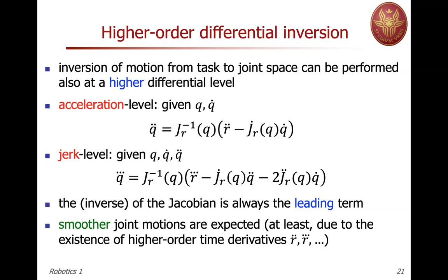If you take a bang-bang acceleration profile, so maximum acceleration and maximum deceleration, then if you look at the third derivative, the jerk, you have an impulse at time 0, an impulse when you switch from maximum to minimum acceleration, and an impulse when you stop. An impulse function cannot be realized in practice.